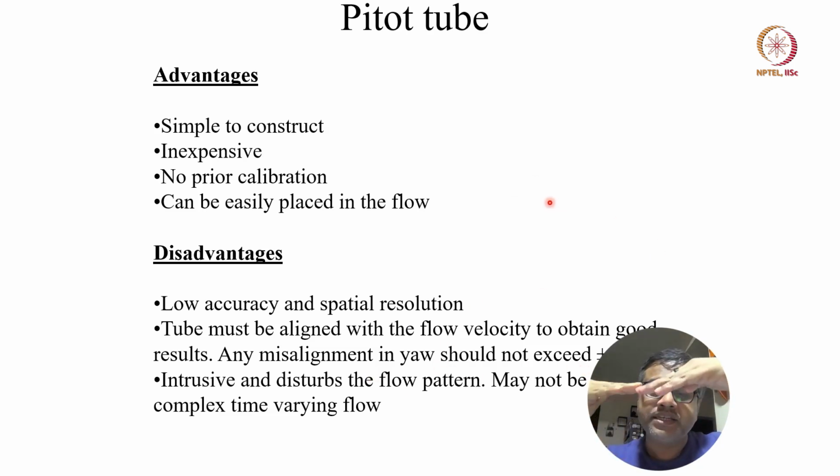The tube also must be aligned with the flow velocity to obtain good results. Any misalignment in the yaw should not exceed a certain degree. And it is intrusive and it disturbs the flow pattern.